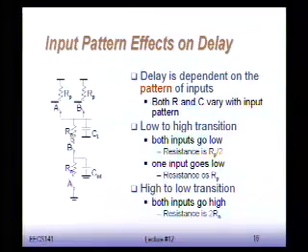So what happens then is that this switch is closed all the time, right? B, we said, is constant at 1. And this switch is open all the time. Still, when you pull down A, this switch is open, so the output doesn't have a path to ground anymore. And this other switch here is closed, so there is now a low impedance path of the output towards the supply. So the output is going to get pulled up towards the supply now.